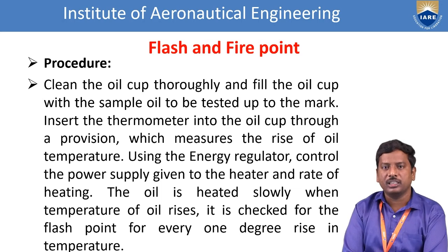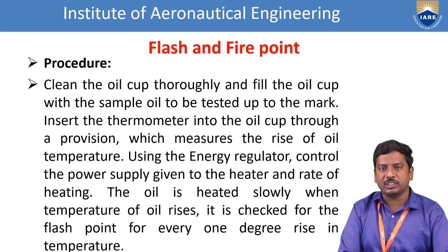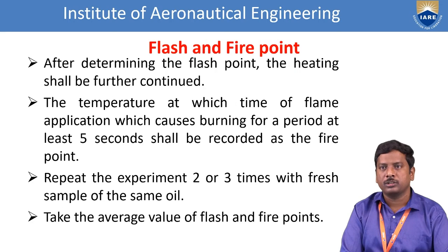Okay, so this is the first step of the procedure. After determining the flash point, the heating shall be continued further. The temperature at which the flame application causes burning for a period of at least 5 seconds shall be recorded as the fire point.